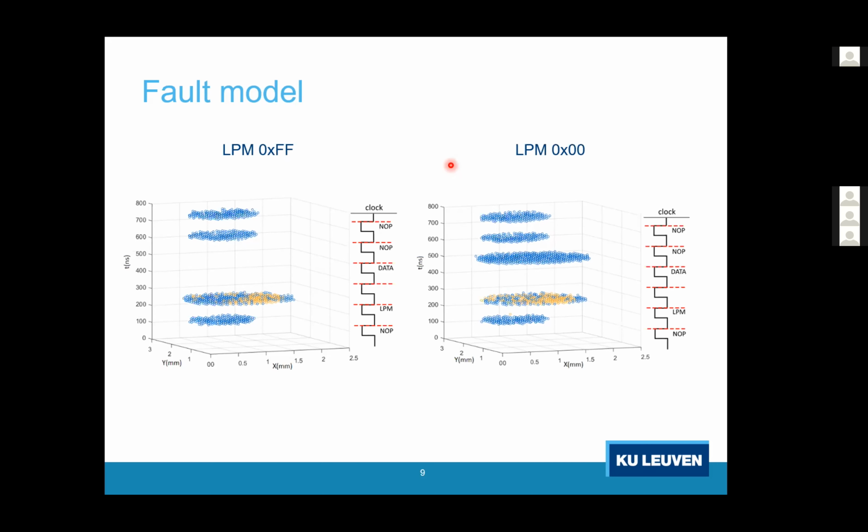What's also interesting on this picture is that all the faults are injected right around the clock edge, it seems, and the intervals between the faults are nicely 125 nanoseconds. Which means that we're only able to fault the device around the clock edge. When constructing this figure, we injected faults every 10 nanoseconds.